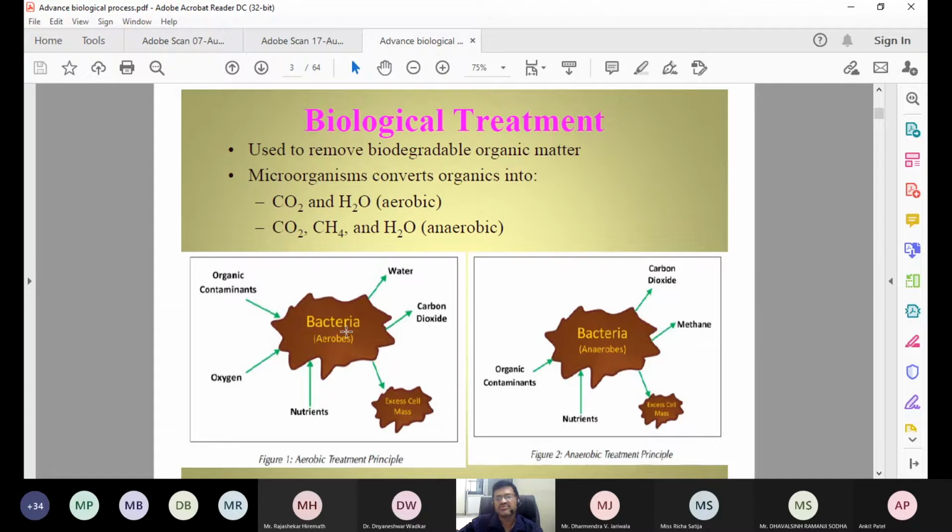So they are consuming the organic matter and oxygen, and they are giving water and carbon dioxide, and getting food. That waste they will consume, but what else are they consuming? They are consuming oxygen also. From where? From the river. Whatever dissolved oxygen is there in the river, they are consuming it with the organic matter. That is the respiration reaction for getting energy.